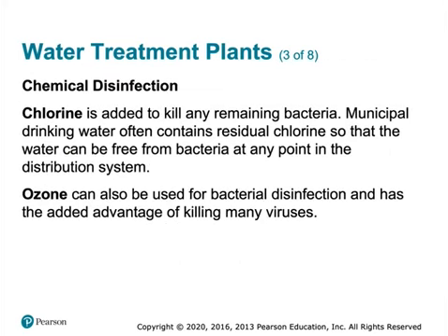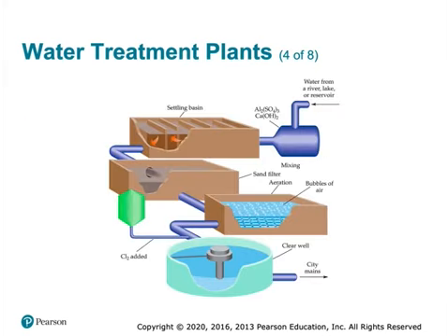And then typically we use chlorine or ozone to treat it, to get rid of the bacteria. This is very often used. Chlorine is the most often used. Ultraviolet light can also be used. Various places use ultraviolet light. Maui uses chlorine. Oahu sometimes doesn't use chlorine. It depends on the bacteria level. They test their bacteria level before they distribute the water in Oahu. They just chlorinate the water in Maui.